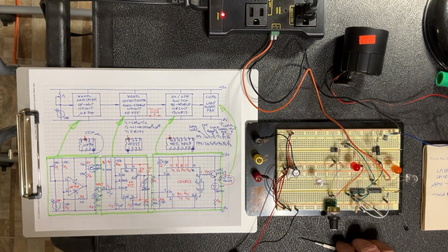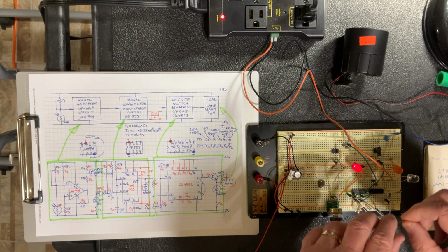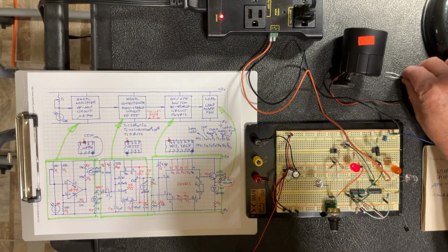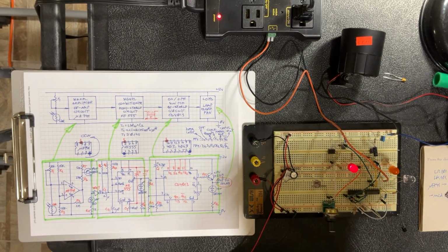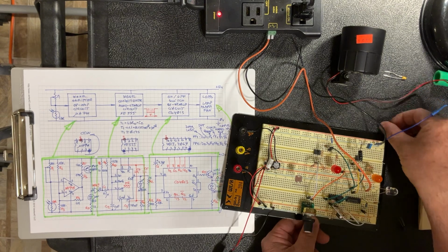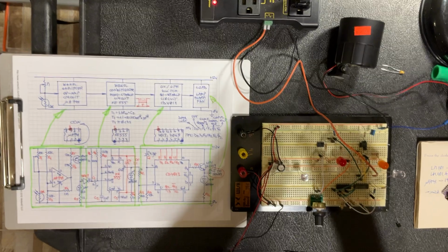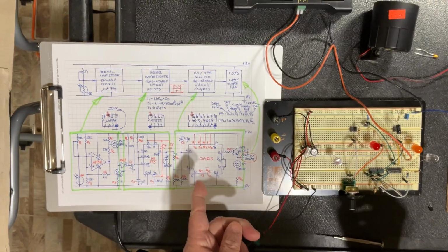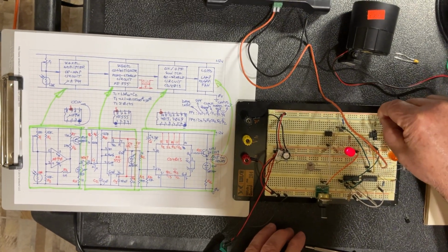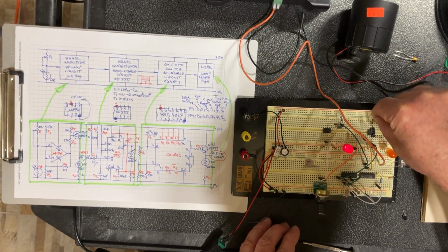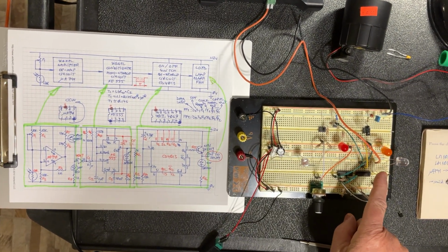Just to make you understand how this works, I'm going to remove this little capacitor here, which is 1 microfarad. I'm going to put it aside, and I'm going to replace it by another one. I have it right here, which is this one, 10 microfarads. So instead of being 0.14 seconds, it should be something like 1.5 seconds, so longer. You should be able to see it. So take a look at how long the amber stays on.